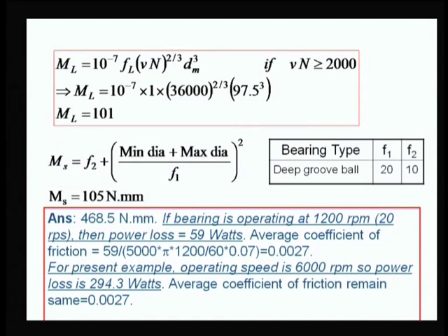So to think about that, we can think about the temperature. However, there's one exclamation mark that comes over here. This is a loss in a bearing. And if we talk about the 6000, the 5 times of that is on the higher side. So almost 295 watts have been lost in the bearing, and still we are calling this an anti-friction bearing. So we need to think whether we should call this kind of bearing anti-friction, or we should call it only a rolling element bearing. I prefer to call this a rolling element bearing compared to an anti-friction bearing.